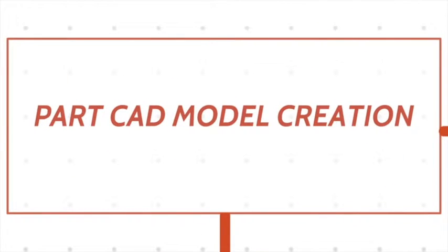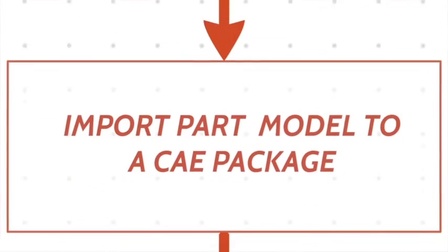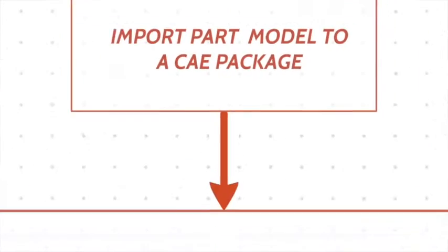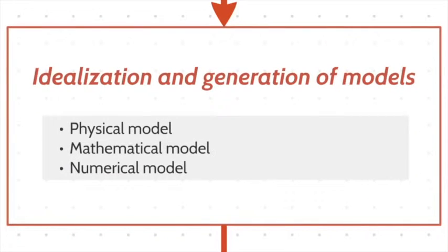But first of all, we need a CAD model of something that we're going to mold. And then following that, we have to import that design into a mold flow software using file types such as STEP or IGES. And then we need to create our simulation to set it up. For that, first we need the physical models, where we have to firstly define whether it's a 2D or a 3D model. And then we have to select our material as well as the boundary conditions and constraints.